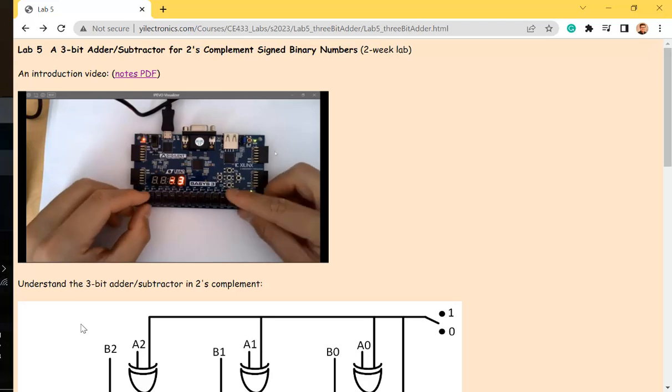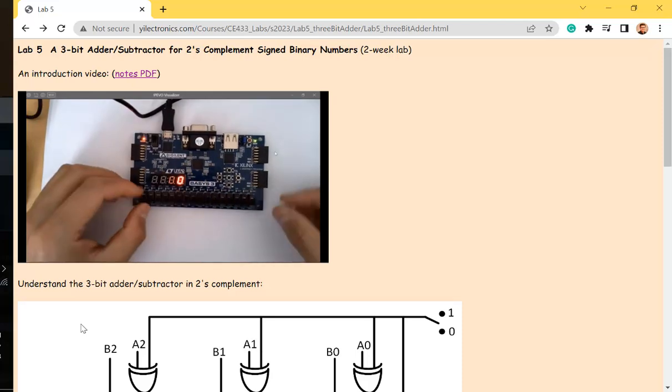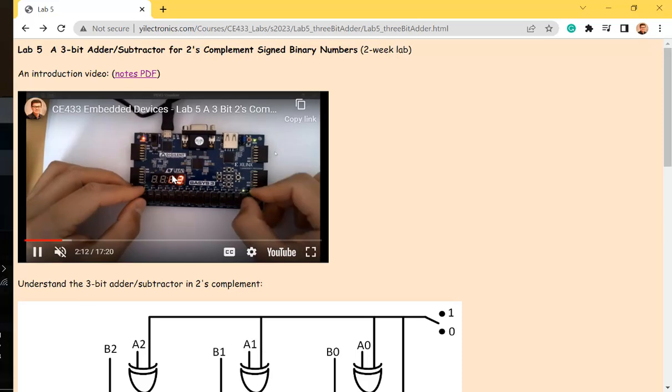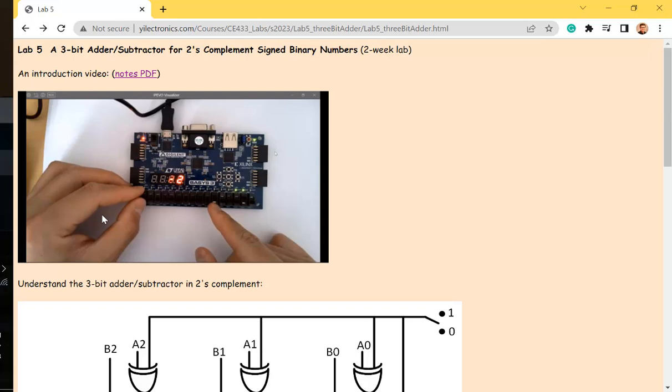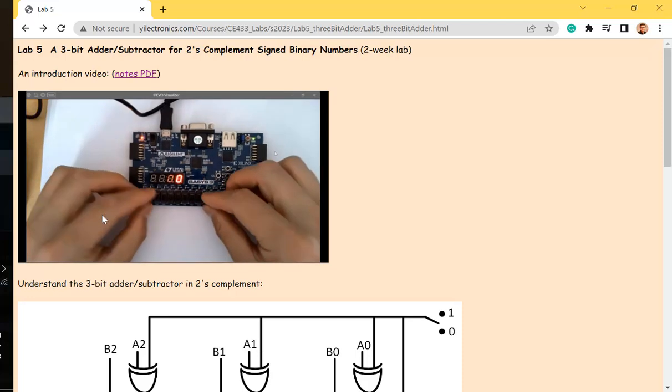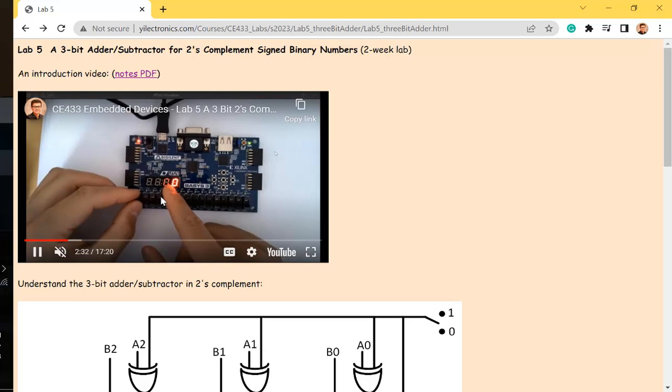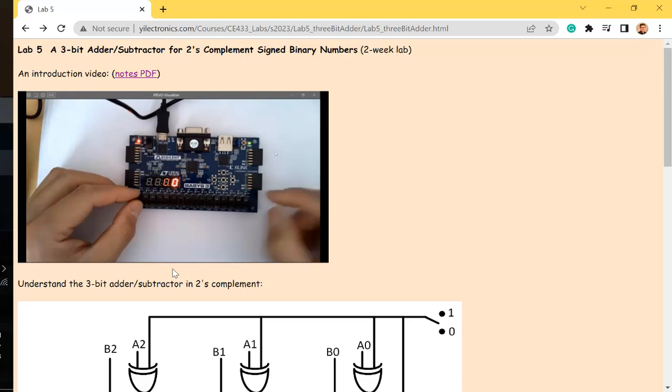If you have to show a negative number, you can see this is not perfectly clean because of the time delay I had in the Verilog code. You can modify that time delay when you scan through in between the 2 units. I forgot whether increasing or decreasing it removes that kind of ghost digit on that unit, right? It's working. It's not too bad.